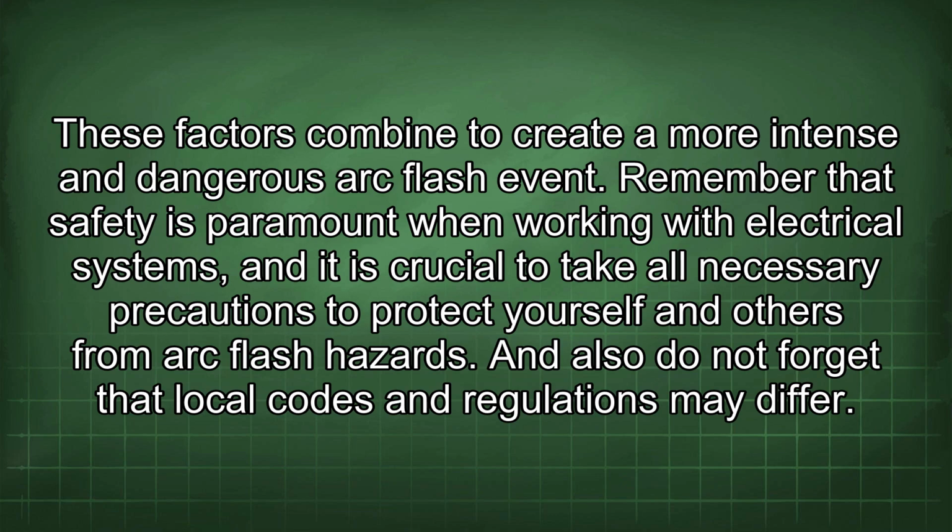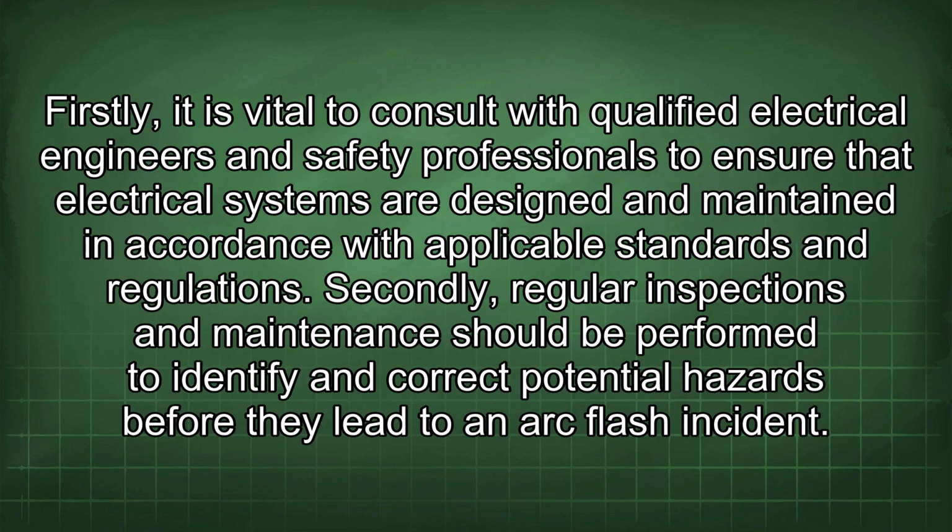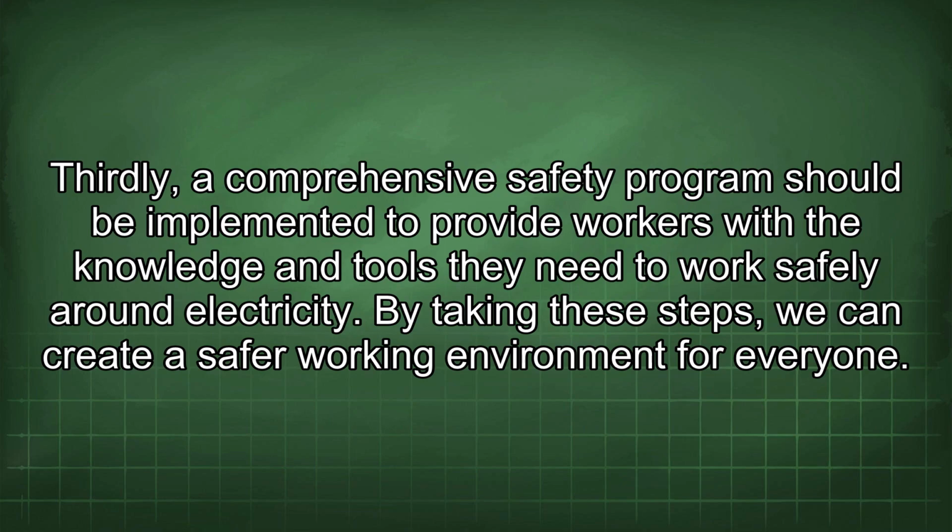And also do not forget that local codes and regulations may differ. Firstly, it is vital to consult with qualified electrical engineers and safety professionals to ensure that electrical systems are designed and maintained in accordance with applicable standards and regulations. Secondly, regular inspections and maintenance should be performed to identify and correct potential hazards before they lead to an arc flash incident. Thirdly, a comprehensive safety program should be implemented to provide workers with the knowledge and tools they need to work safely around electricity. By taking these steps, we can create a safer working environment for everyone.